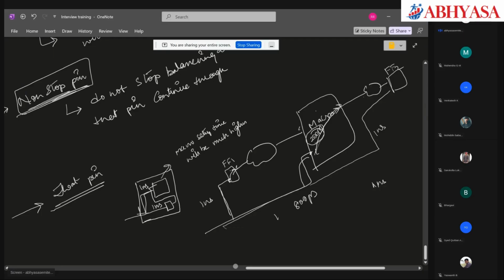If we say the macro clock pin is a float pin and mention it already has 200 ps of internal delay, we are just bluffing the CTS engine, saying that my macro already has an internal insertion delay of 200 ps. So the tool, instead of building the latency or the clock for 1 ns, will build for 800 ps. Now if it builds for 800 ps, I will have a good positive skew of 200 ps.